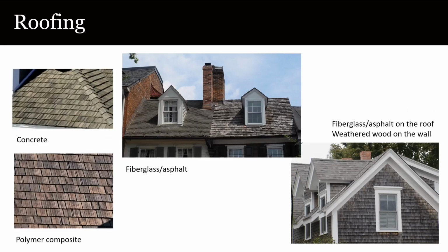Wood shingles have too short a lifespan to survive long enough to often become historic. Even when a building still has a wood roof, it's likely to be a second-generation one. Many projects are looking to reestablish the appearance of a wood roof long gone when it's known that that was the historic roofing material. Wood shingle roofs present a significant challenge for matching with any substitute material, though wood shingle substitutes are produced in both concrete and polymer composites.